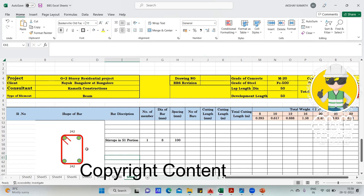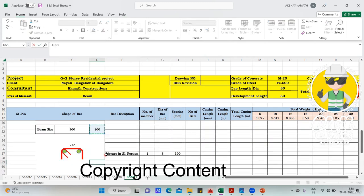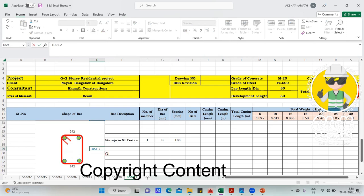Okay, done. No? And now this portion, how much is it? Plus, you should interlink here 400 minus 25 top minus 25 bottom minus diameter of the bar 8, finish. It should be 342 and I got it. Bring it here. Okay, it will come only this much. I'll drag it like this. Then I think it should come here. Okay, now it's okay. 342 and plus this one, enter.